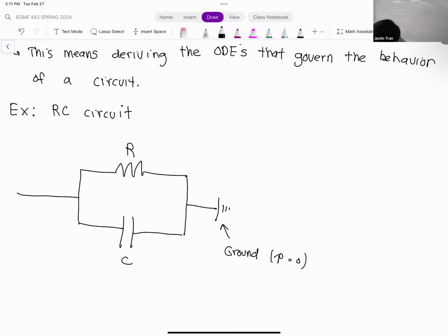This simple RC, this resistance capacitance circuit, in fluid mechanics is what's called a 2-element Windkessel model. If you think back to the Windkessel model that we talked about in the beginning of class today, a Windkessel model is comprised of a flexible chamber, represented by the capacitance or the compliance, and it's also represented by your highly viscous outflow channel, which is given by your resistance here.